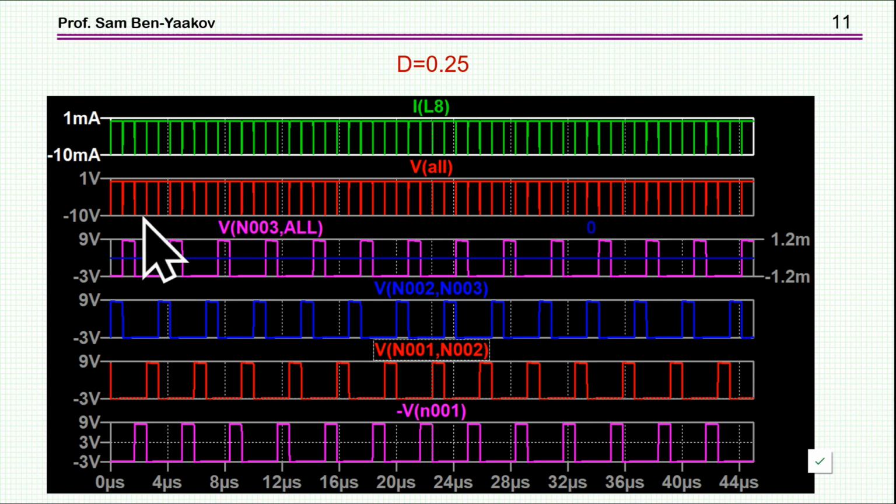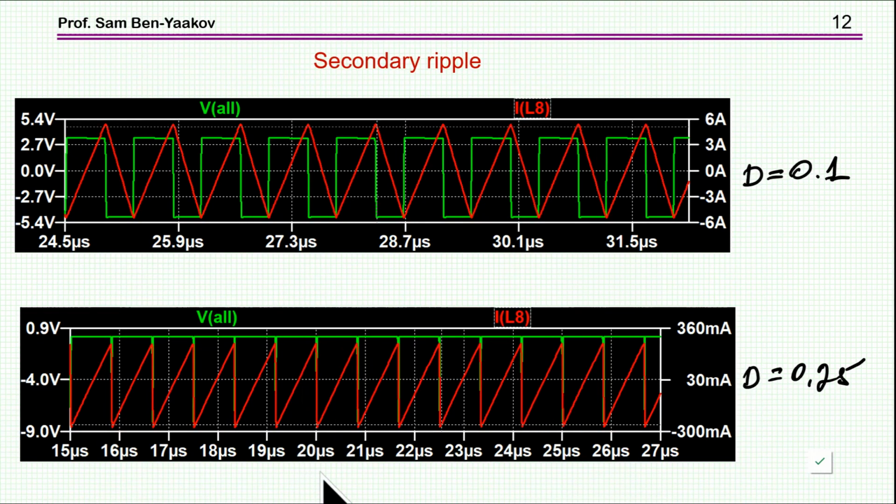Now, due to this voltage, as it is imposed on the inductor, I mean the secondary side inductor, this L sub C plus the leakages, then we're going to have some ripple here. But again, this is the case in which we are sort of filling up the period with these pulses, and consequently the ripple is very, very low. We're talking about milliamps. So this is really a very small ripple. So here is again this case of the 0.25. It's sort of a zoomed picture.